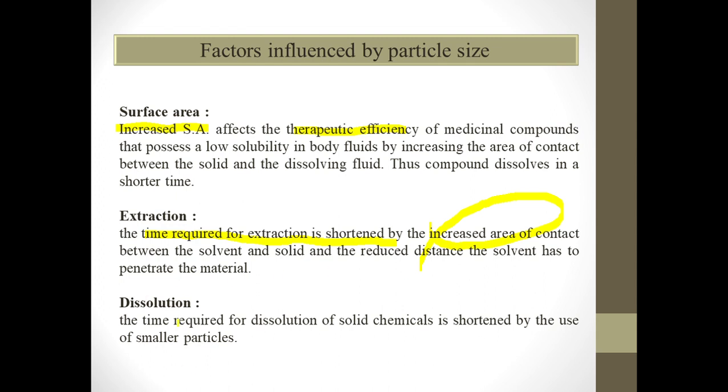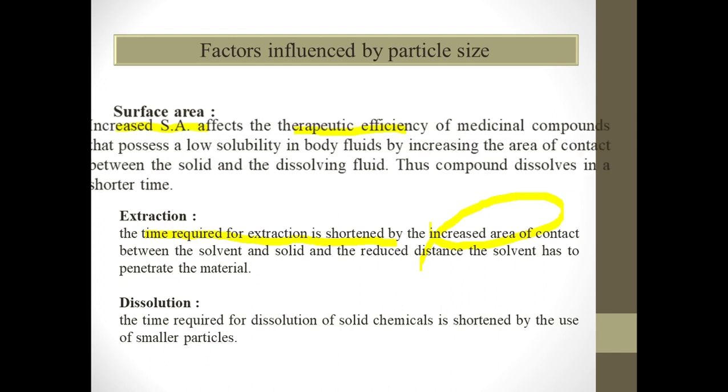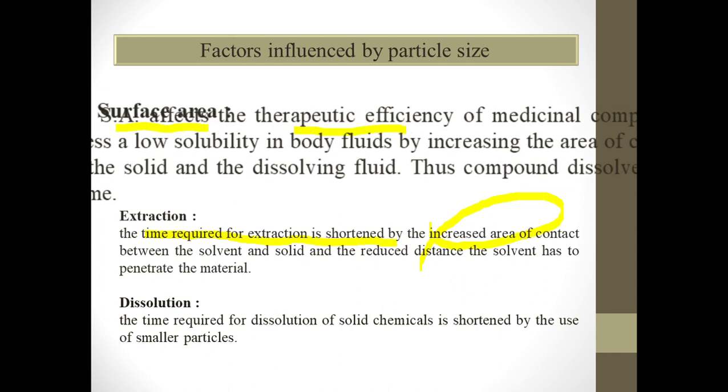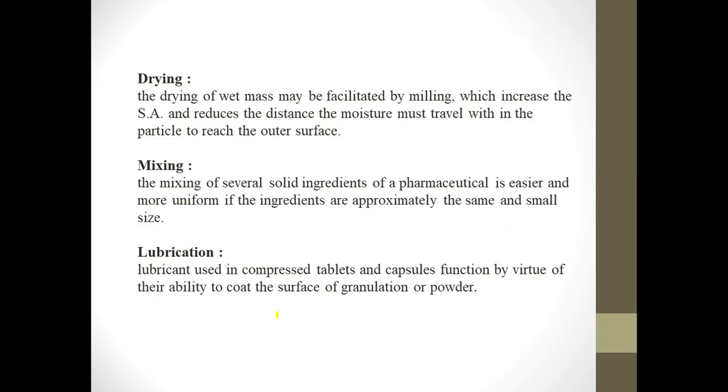Dissolution is shortened by the use of smaller particles, so when you use smaller particles, you get better dissolution. Drying: the smaller the particle, the faster is the drying, and the faster the moisture moves away. Drying of the wet mass will be facilitated by milling.